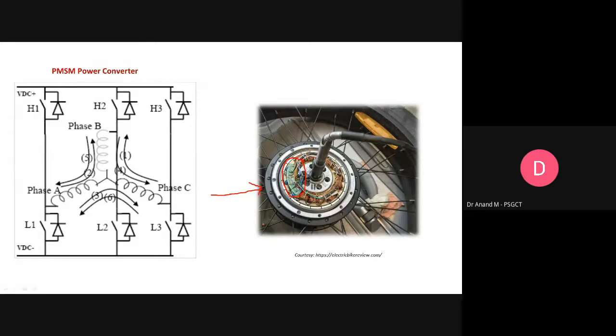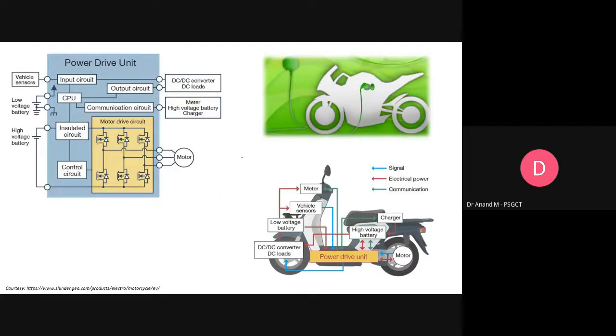Now the recent trend in research on e-vehicles concentrates on the type of material that we can go for, maybe a controllable device, or a power semiconductor device acting as a freewheeling component. For example, for a two-wheeler segment, as you can see from this slide, implementing MOSFET-based driver controls, can I make any change with respect to the semiconductor materials? Recently, we have been sticking with silicon-based devices, but especially for e-vehicle applications, several branded OEMs are now thinking about WBG-based devices, the wide bandgap devices, so maybe silicon carbide, gallium nitride, etc.